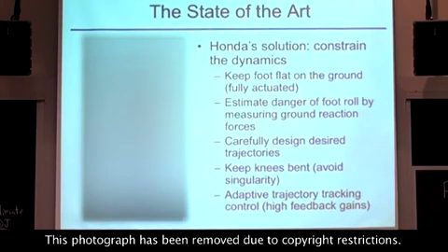They assume that their foot is bolted to the ground, which would make them fully actuated, right? And then they do a lot of work to make sure that that assumption stays valid. So they're constantly estimating the center of pressure of that foot and trying to keep it inside the foot, which means the foot will not tip. If you've heard of ZMP control, that's the ZMP control idea.